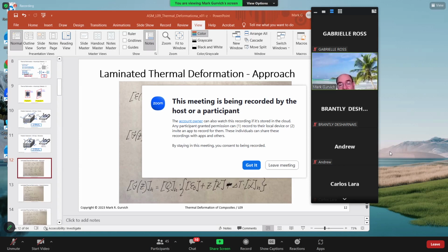Excellent question. And it actually has a very practical definition for why to use it. I have a special slide on that, because for example, if you have a piece of material restricted, with no opportunity to move, and you heat it, it will be under compression. If you cool it, it will be under tension. So depending on what boundary conditions you have, you can create extra compression, extra tension, extra shear, actually extra bending.